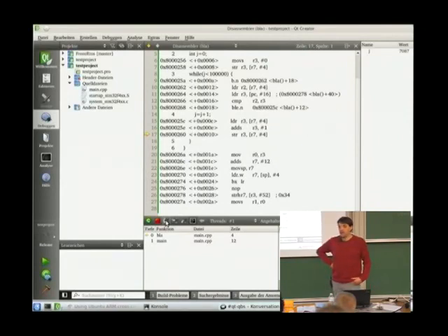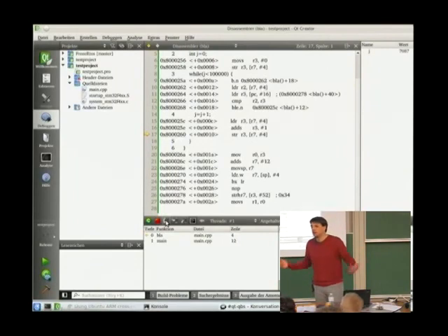Memory map, I don't know. Well, one thing was stuff that you have in device maps. The memory map is an output of the compiler. Yeah. Okay. You can create in Cubes a compiler setting where you just say create me a map, and then it creates a file, and you can just look at it. So well, you got it somehow.